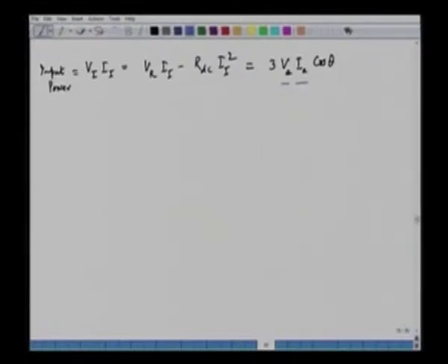So if we draw the phasor diagram here, we can start with, let us say, the field axis. So this is our field axis. We can say this is the D axis. We can show the field pole like this. This shows the field of the synchronous machine, and then the Q axis is at right angle to the D axis. So this is our Q axis, and this angle is 90 degrees, and of course the field current is in the direction of the field axis. So we can say this vector is IF, IF is in the d axis, and the field current IF induces some open circuit voltage, that voltage is in the q axis. So this is our EF.